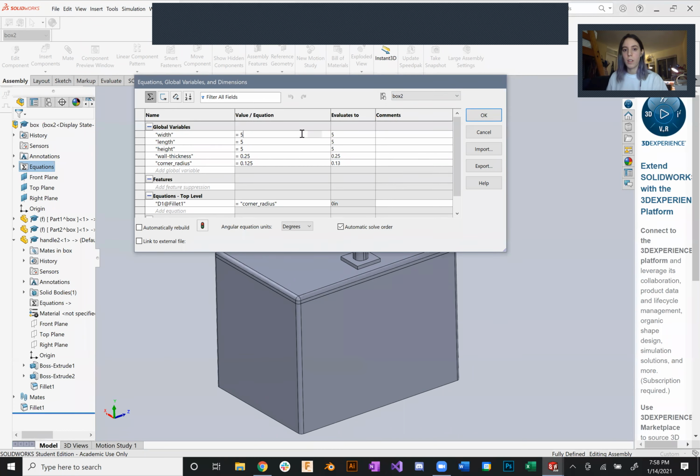What I have to do is click on this and then a window shows up that's previously invisible, which is how amazing SolidWorks is at hiding the configuration menus. It doesn't even show up until you click. So I'm going to change it from all configurations to this configuration. And I'm just going to change these three variables, and I'll just change them to something else.